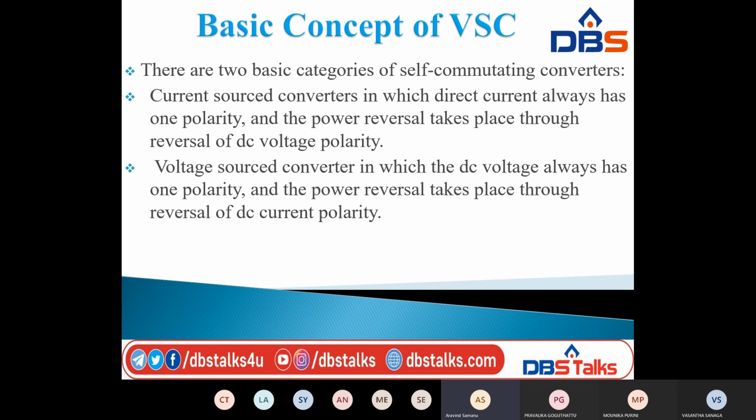Current source converters are those in which the direct current, that is the DC current, always has one polarity, and the power reversal takes place through reversal of DC voltage polarity. And the next one is the voltage source converter.